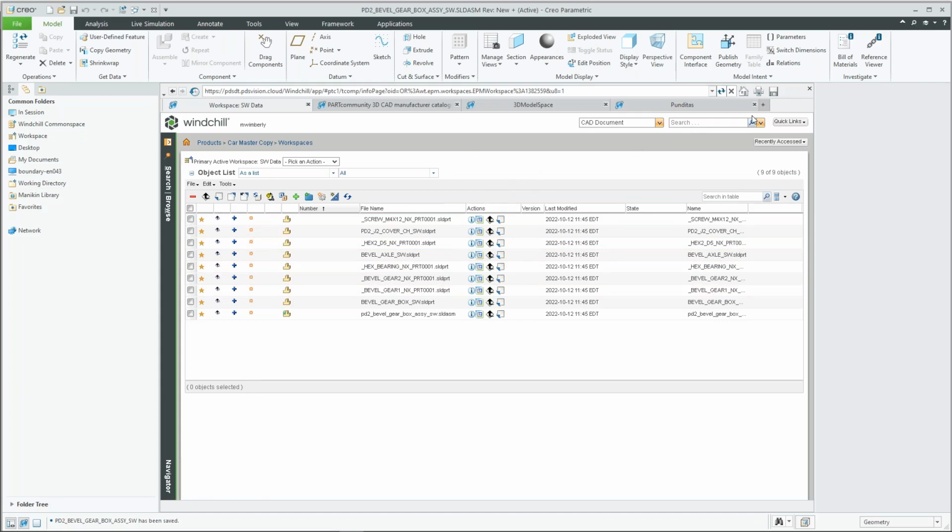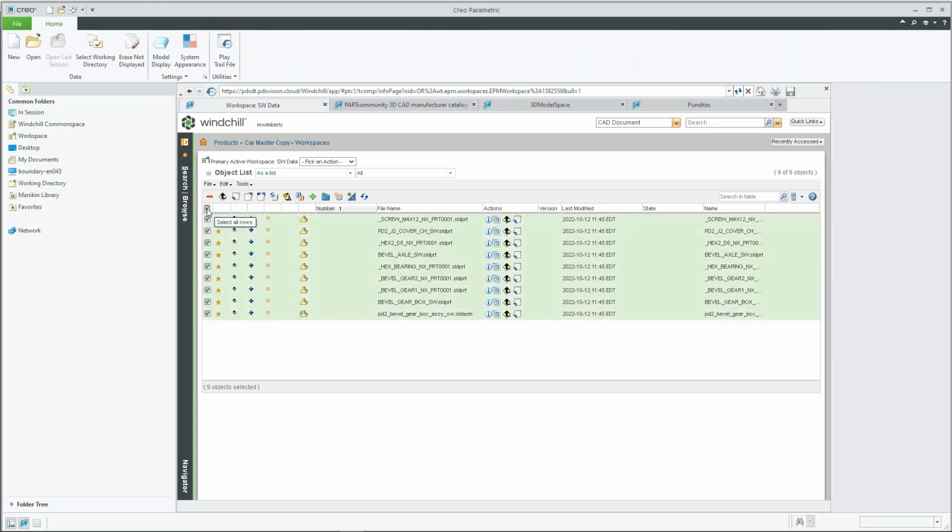So as I said, I can open this up and store it inside of Windchill. Once again, I'm not tying it to SolidWorks at this point. What I'm actually tying it to is Creo. So because I don't have the Workgroup Manager, when I go to open it, it's going to open this file in Creo, not look for SolidWorks. So with that, once again, I'll go ahead and close the assembly, which was behind it. I'm now inside of my workspace.